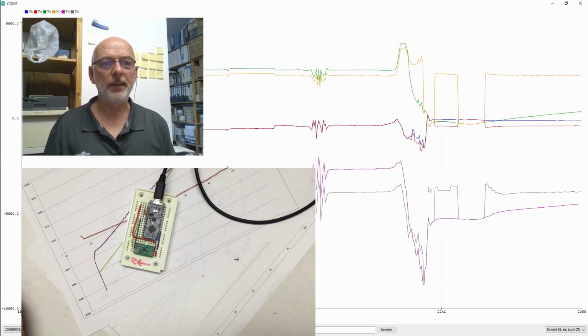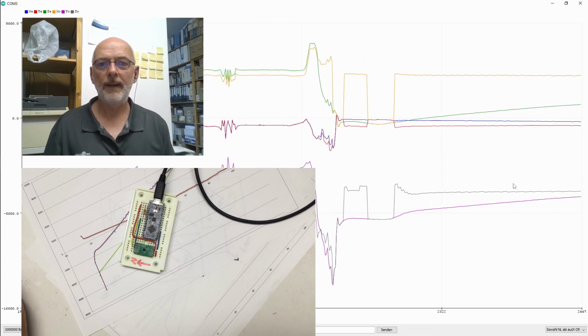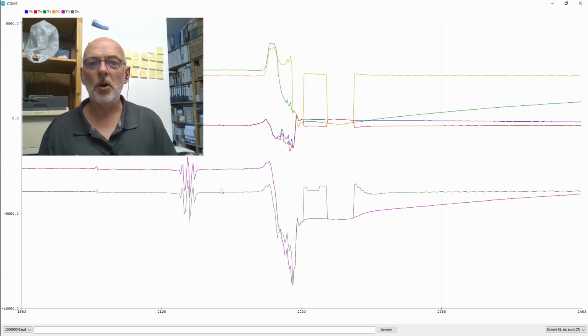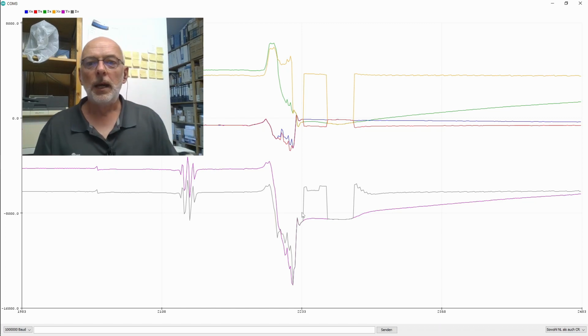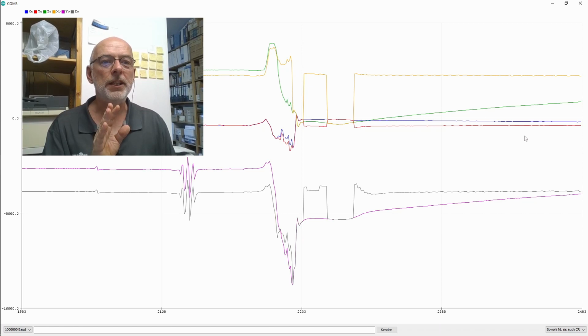And you see here very nicely, I will stop it in a second now. About now. You see here, that's our temperature compensated curve. And while I spray that thing, I disturb the magnetic field and everything is a little bit disturbed. But you see, this is our compensated curve here. And it's absolutely unfazed by the temperature change. While lilac here, our uncompensated curve for the z-axis, it drops and it only slowly recovers as the temperature of our chip rises again.